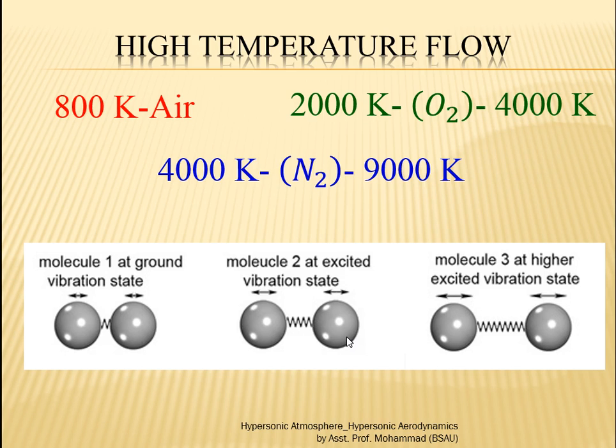So the two assumptions we normally make here depend upon the fluid velocity at the molecular level, the molecular vibration and excitation, and the mainstream flow. Depending upon their relative motion, we normally have two types of concepts in the case of flow. We make two assumptions. If the microscopic changes or reactions are at a faster rate than the movement of the fluid, then it is treated as equilibrium flow. It's in equilibrium because it's very fast. Otherwise, it is treated as non-equilibrium flow, which is difficult to analyze.